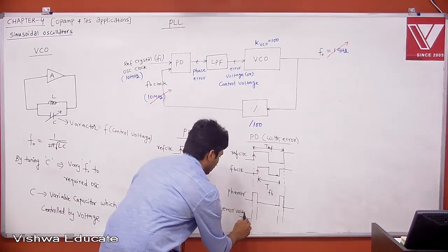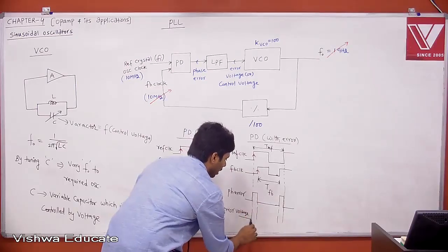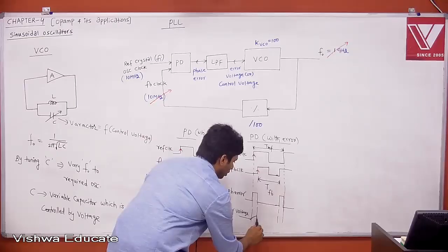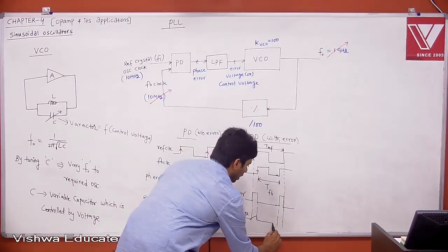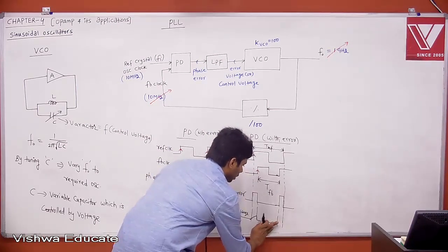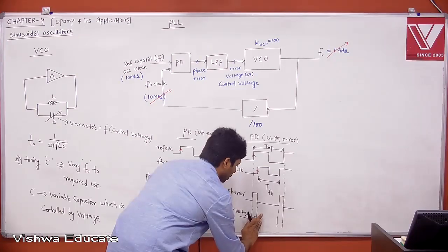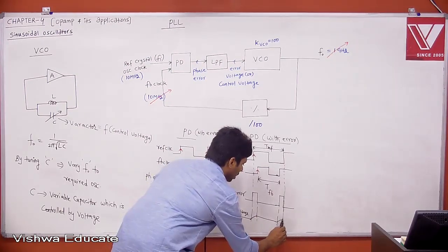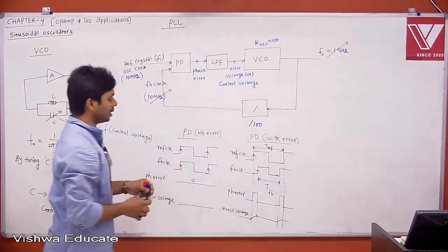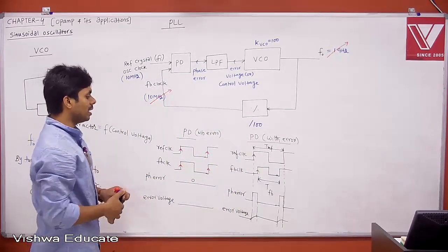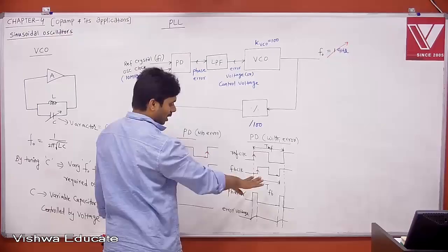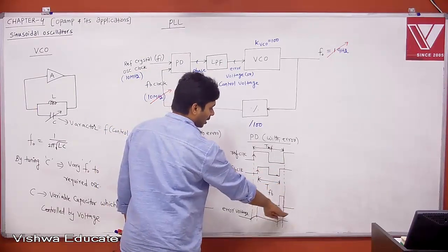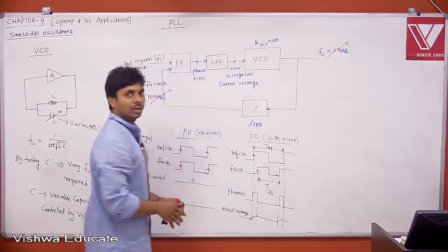But now whatever constant you have, this is your error voltage. Because it is high, it will be charged. It is trying to charge. Again, if there is an error, it will be charged to that level, and it will stay. And again if there is error, it will again try to charge. The error voltage is given to an RC circuit. The capacitor will be charged, then it will not discharge immediately, it is holding, and with the next phase error, slowly it is going to increase.